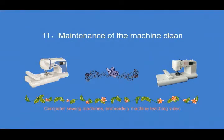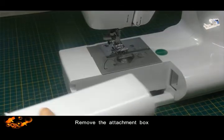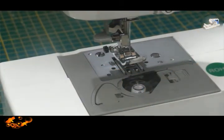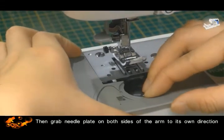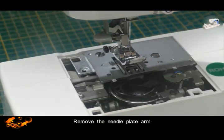11. Maintenance and cleaning of the machine. Shut off the power. Remove the attachment box. Open the needle plate cover. Remove the bobbin. Then grab the needle plate on both sides and pull it toward yourself. Remove the needle plate.